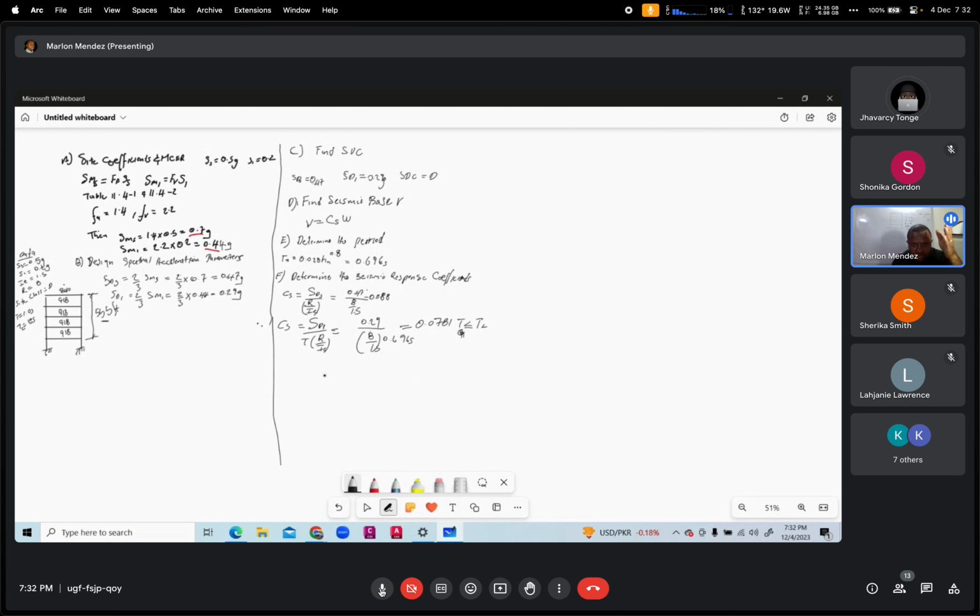Whatever the fundamental period is, this equation applies when T, or Ta, is less than TL, and it uses the design spectral response parameter at a 1 second period.